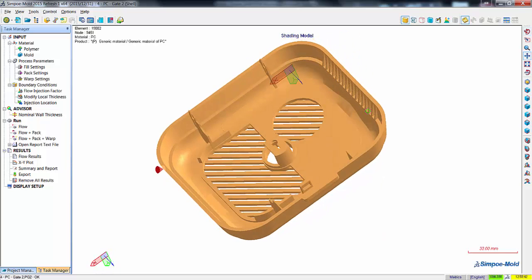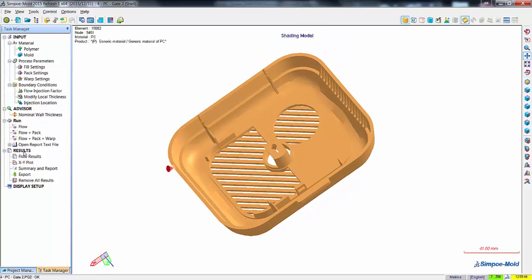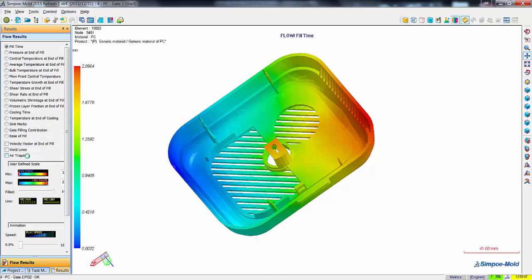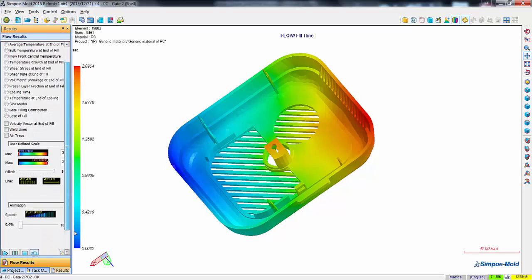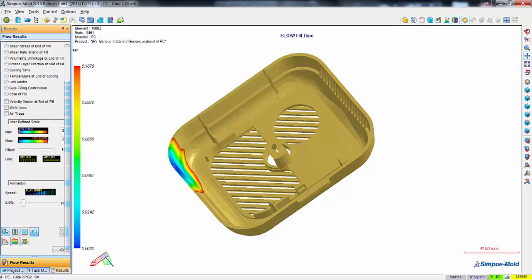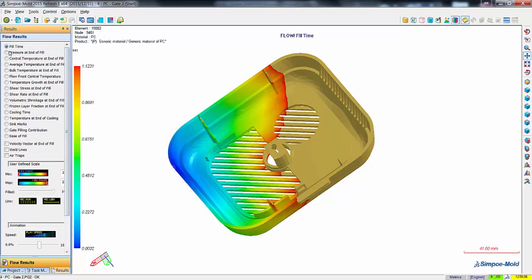From the results, we see that the new injection location definitely helps to significantly reduce the weld lines, especially on the rib. However, you can see that with nearly 47 megapascals, our pressure to fill is still higher than preferred. If we were only considering a single cavity mold, our required pressure would work. In this case, we will be considering a multiple cavity mold and must consider the increase of the injection pressure requirement by adding a sprue and runner system. Another change will be required.